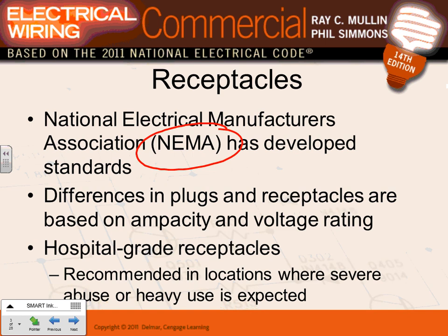Receptacles are weirdos because they can go to different voltages, different amps, right? You can have a receptacle that runs at 480, 277, 50 amps, 3-phase, and a receptacle like that one that you're looking at, 15 amp, 120 single phase. Cool? So NEMA developed the standard, thank God for this. You're going to have a receptacle and a plug, and we'll look at these. NEMA rated them based on what the receptacle is and what the plug is that matches the receptacle. You're looking at that one right up there.